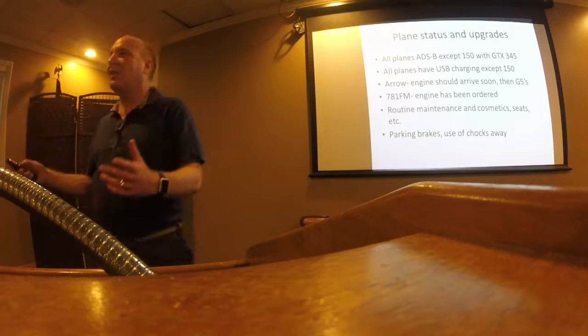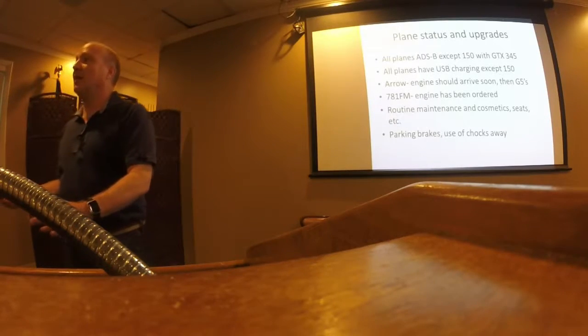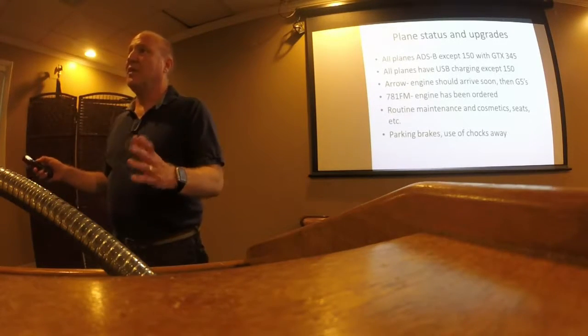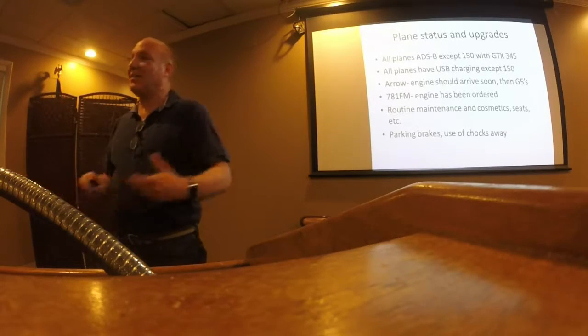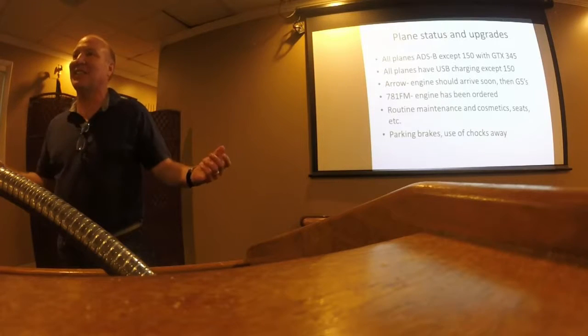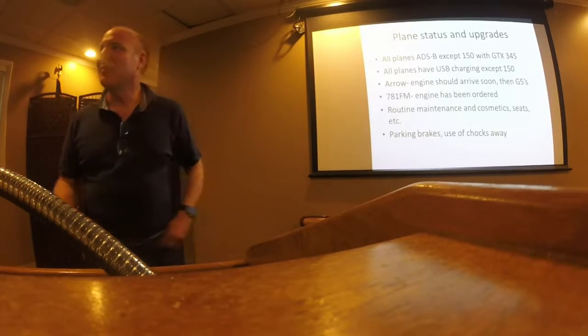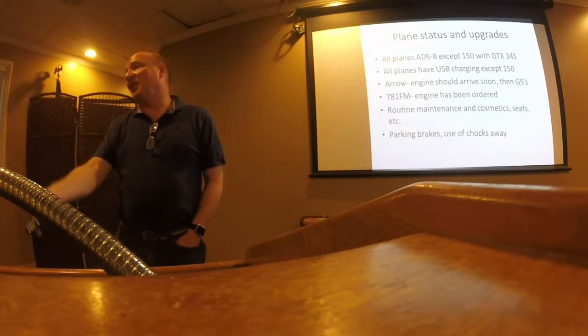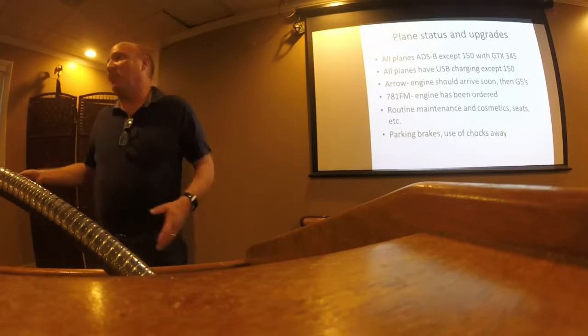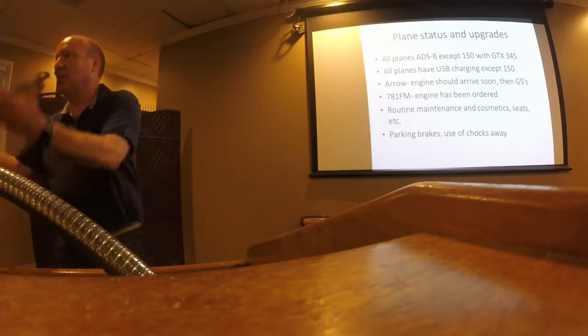When you get somewhere, chock your plane but leave the brakes off, because otherwise they're just going to hook up the plane and drag it with the brakes set. By the way, we are not locking our doors. True, but it depends. You could lock the door and leave the brakes off. If you've got equipment in the plane, lock the door so they can't get in, but they can tow it.